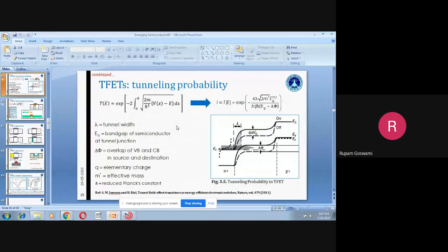Whenever we are doing temperature analysis for a device on a TCAD tool, we first of all try to vary the ambient temperature of the device, or the lattice temperature, which is more specific. Secondly, you need to tune your models with respect to those temperatures, because most of the experiments are based on fabrications done at room temperature. So you need to get hold of an experimental device which can give you a calibrated curve for a lower temperature or a higher temperature than room temperature.